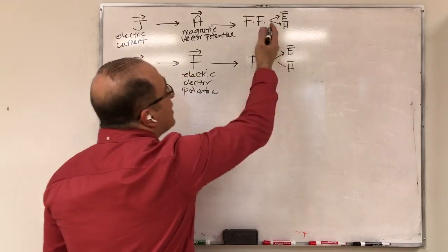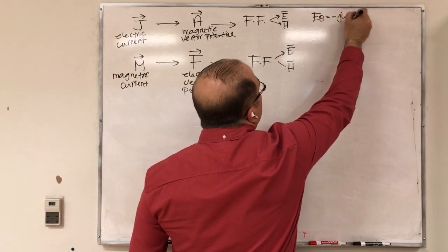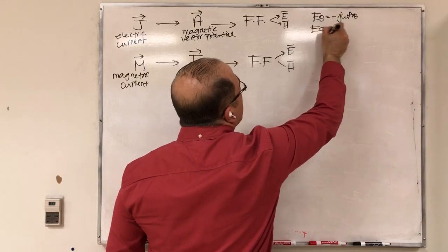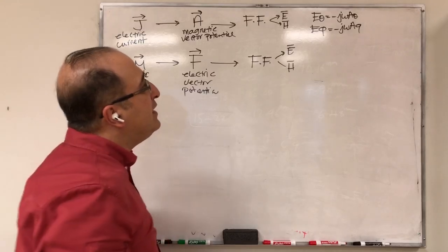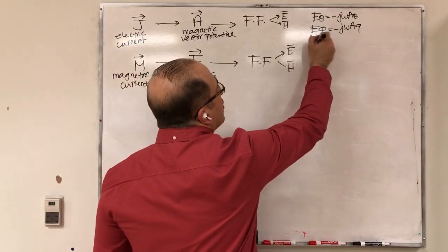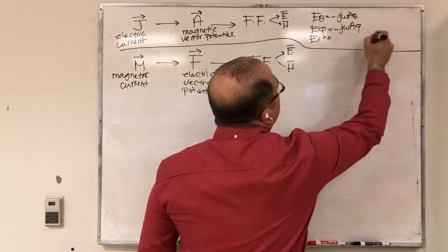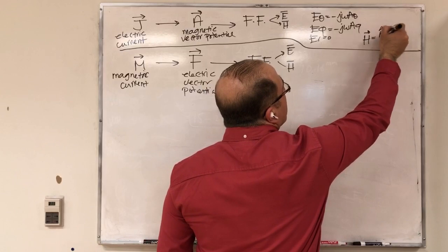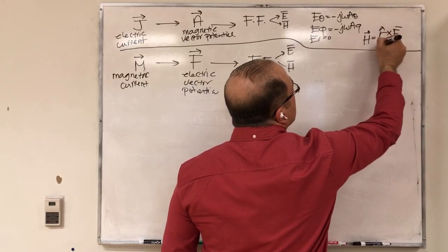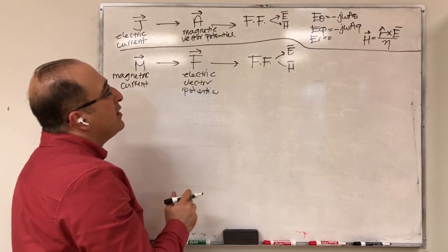And then I can just write it here too. E theta becomes minus j omega A theta. E phi becomes minus j omega A phi. And we know that E R is 0. And then we can find H, because we are in the far field, we can do plane wave approximation. R hat is the direction of propagation, so we have everything.